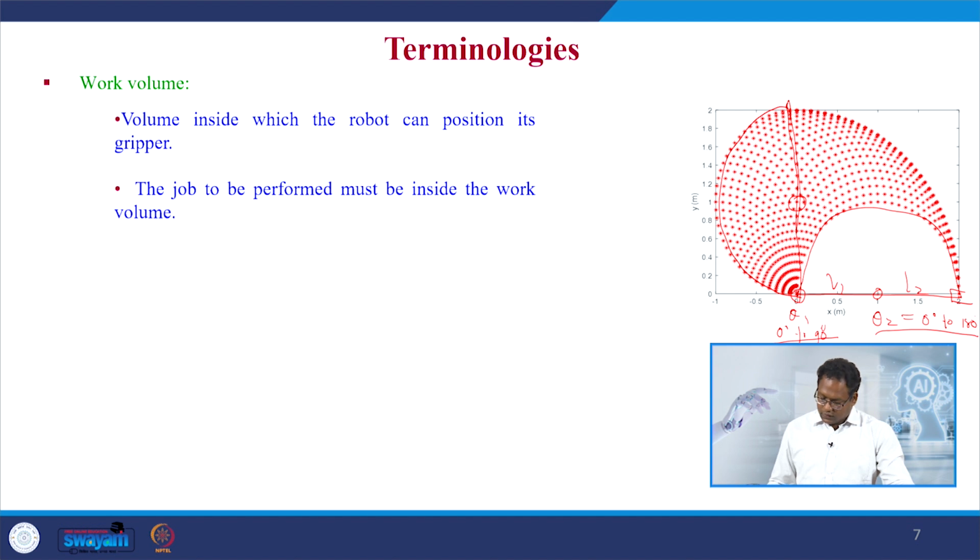So, what is observed here is we have this region as a work volume and we have obtained this region as the work volume line. Then you keep this, for example, you keep here 90 degree for theta 1 and theta 2 is also 90 degree, and then keep theta 2 at 0 degree and move, you have this one coming into the work volume.